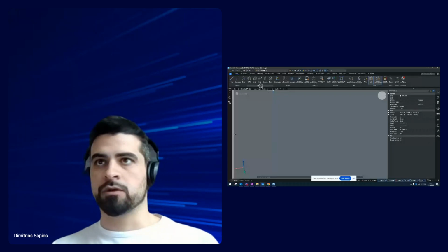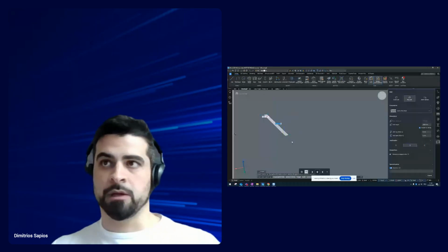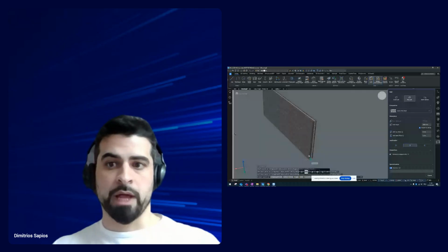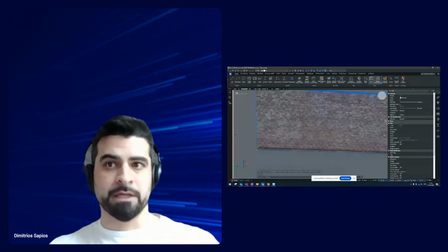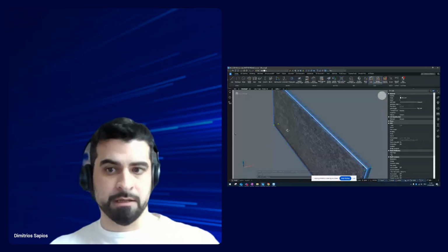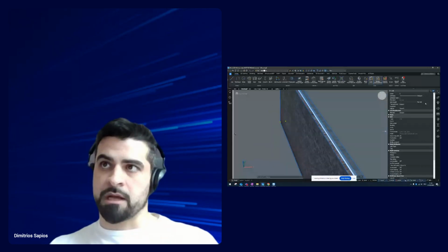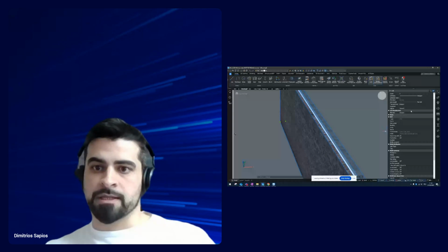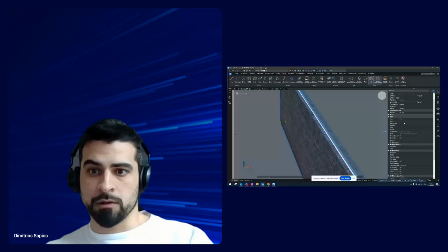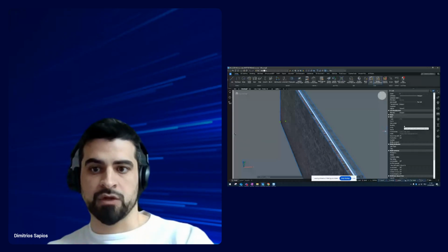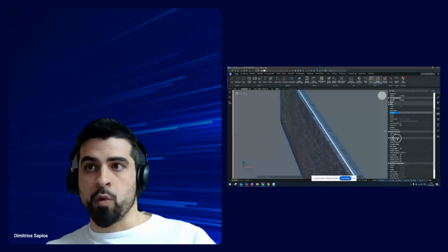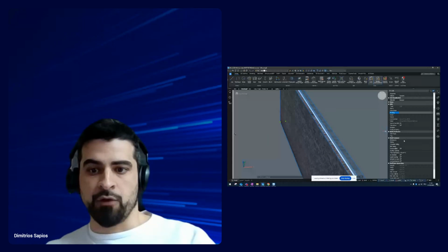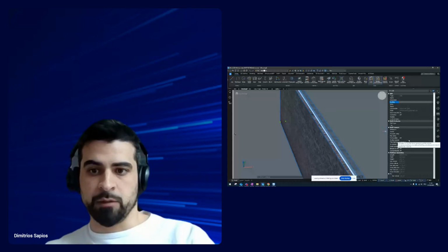In this case, I will just hit on the wall, and with the help of the side panel, I will create an IFC classified wall that already contains materials and BIM metadata. So once we visit the right side on the properties panel, we can see the standard IFC options and properties. This is a BIM wall, so we can insert the standard information about which building it belongs to, which story, and some wall common attributes, some fire ratings, so everything that is available to us.